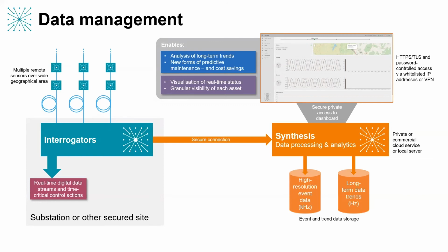And again, maybe one other supplementary comment on that, which comes from our experience in high voltage transmission systems. The Interrogator image that you see here, representative of that 3-unit high rack mounted server unit, imagine that's in the substation. The options available are that this device was designed to output IEC 61850-9-2, so streaming sampled values at around 4 kilohertz publishing rate, because it's expecting to be deployed in a fully digitalized substation, and we've proved that we can do that in the transmission business.